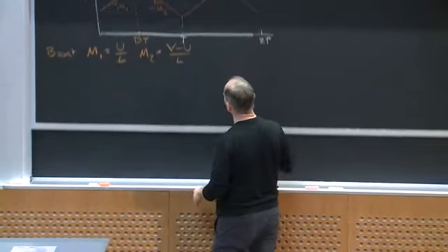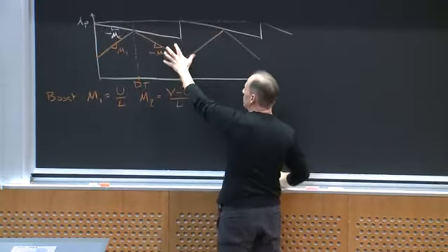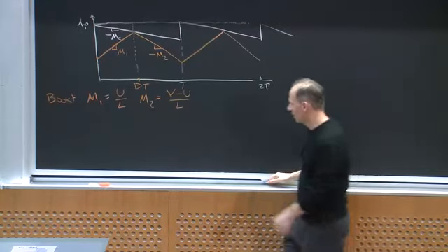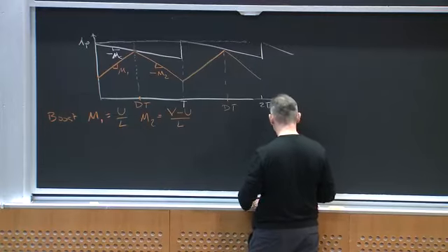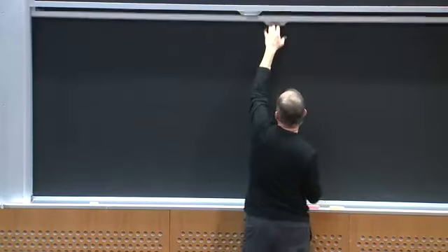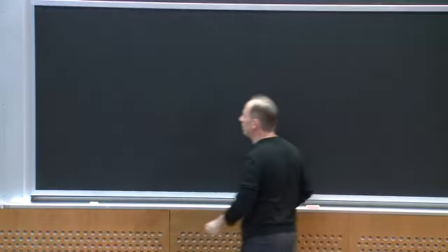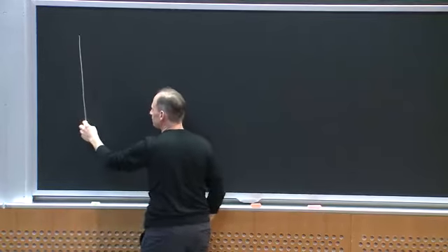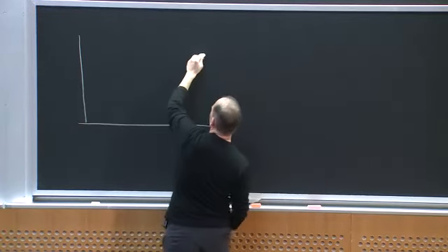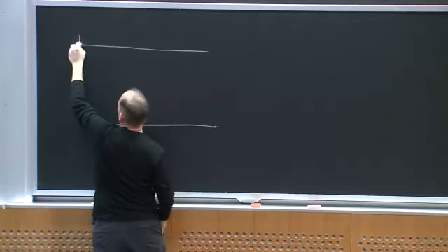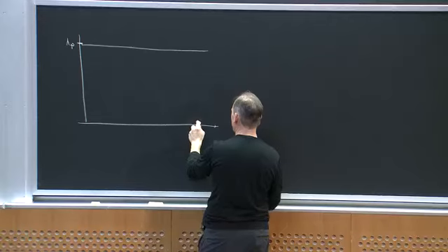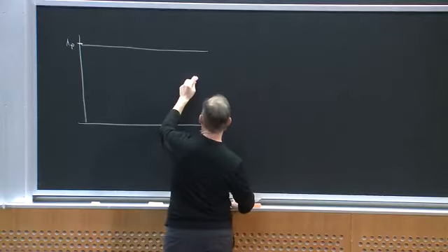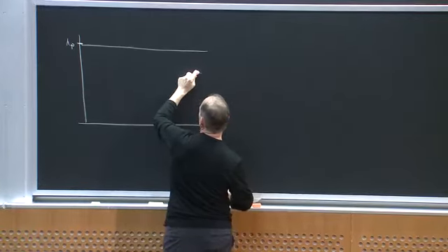And so here's the idea. This picture I drew is actually a periodic steady state picture, right? I used capital D here. I'm assuming it does something every cycle, dT, okay? Let's just draw a slightly better picture for purposes of analysis. Okay, so here we go. Here's my waveform. Here's my peak current. High peak, right? And then I have my so-called compensating ramp, which falls with some slope minus MC.